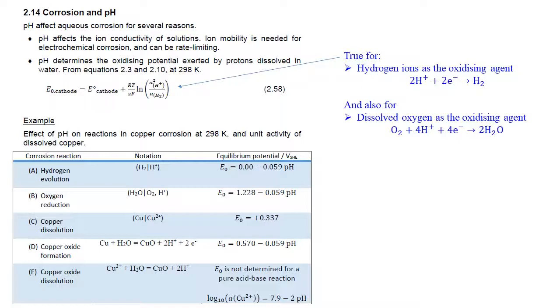That sounds ambitious, but actually we've reached the point where we can see all we really need to know about a corrosive situation is the pH and the mixed surface potential which it exerts on the metal. Both of those are easier to measure in principle for a real piece of metal in the real world, but even more important than being easy to measure is that pH and mixed surface potential taken together tell us everything we need to know about the corrosive chemistry of an aqueous environment.